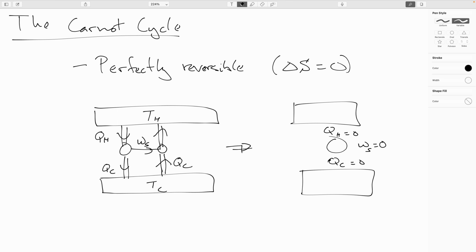So as I alluded to in an earlier video, if we were to have something that was more efficient than a perfectly reversible heat engine, which we can't, but if we could, that would give us something where we could net out having a spontaneous flow of heat from the cold reservoir to the hot. However, we can't have such an engine that's better than a perfectly reversible engine, because then we would be running into the problems of entropy changes not working in both directions.